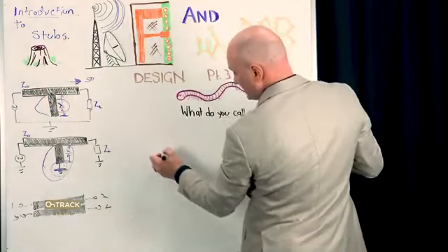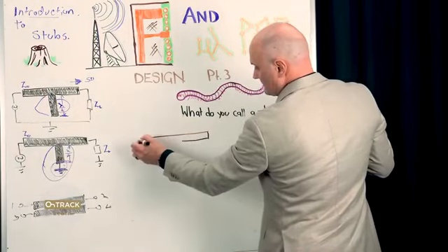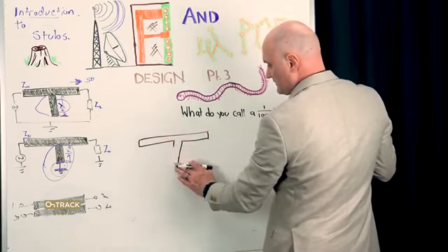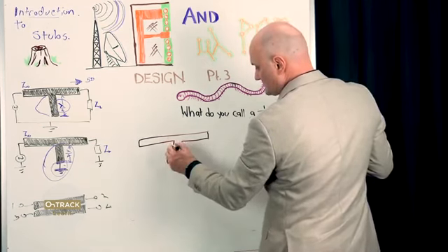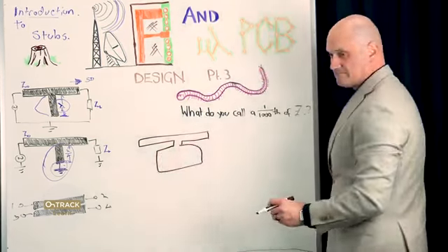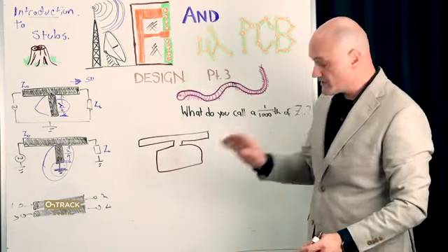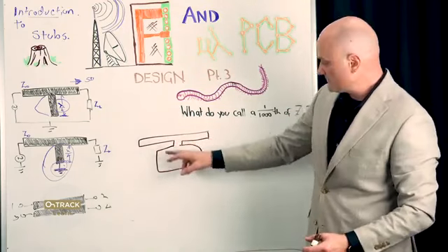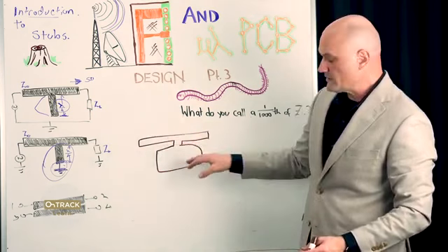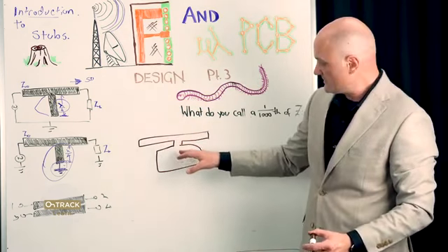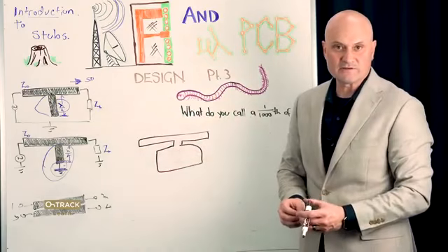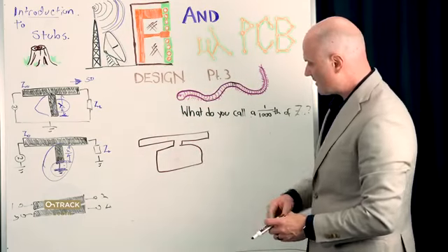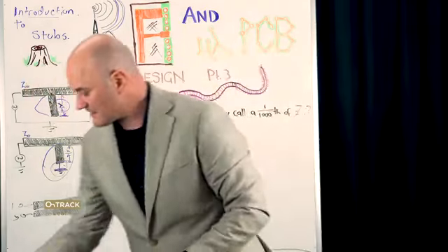We make it bigger. So you can have a transmission line and you can have a stub, and there's a couple of things you can do. You could make part of that stub just a bigger chunk of copper, and you'll see that in some circuits where they need capacitors for a filter. You'll see rectangles, but all sorts of weird radiation modes can happen with rectangles, and we'll talk about that in a couple of episodes away when we discuss antennas, but this could become an antenna unintentionally. So I personally don't like doing things that way.